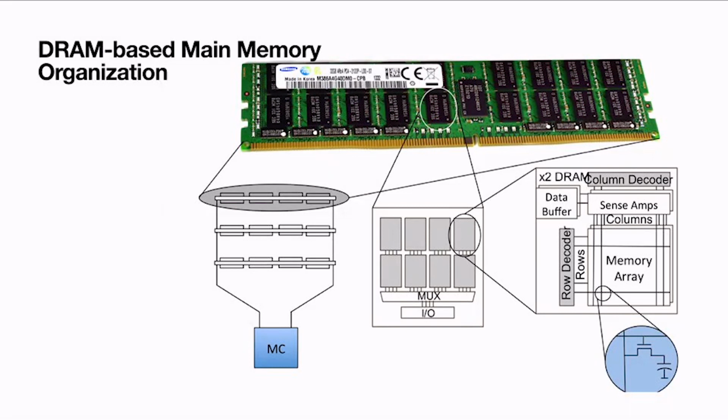You have to do that. Otherwise, the cell is not going to have any charge, and next time if you come to the DRAM cell, nothing will be there. Or it gives wrong information. If it is a true cell and logic 1 was initially stored, it can give you logic 0 because the charge is completely drained. Or if it is an anti-cell and logic 0 is there, next time it is going to say logic 1. So you need to fill the capacitor with the original charge. That is done from the sense amplifier, writing back to the corresponding DRAM cell. That is the restore operation. Okay, all right, so thank you.